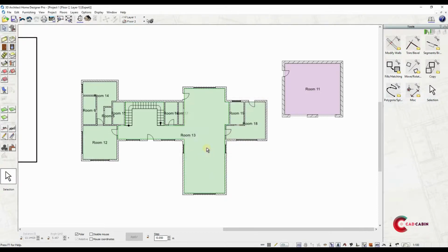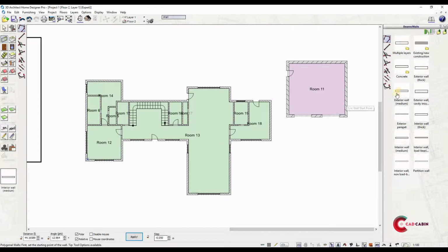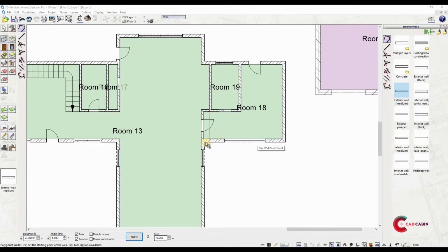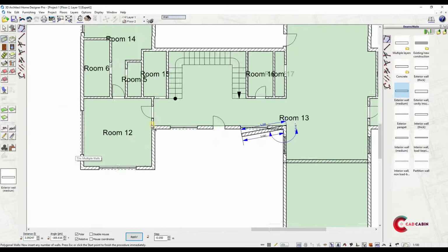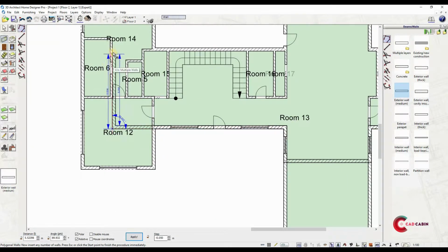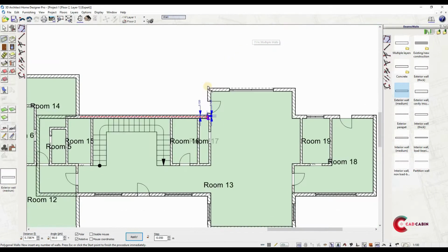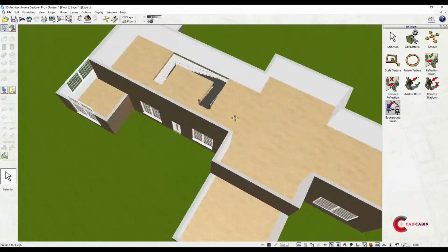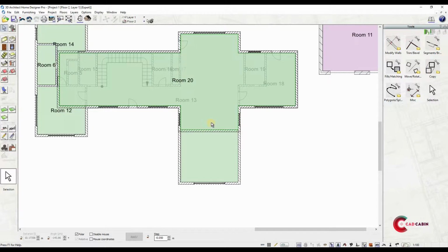In this example, we will not choose to copy the walls and we'll just draw exterior walls manually. By adding the first floor, this automatically changes active floor to the new floor. After that, you can now draw first floor exterior walls. Adding an upper floor automatically cuts out stair area.